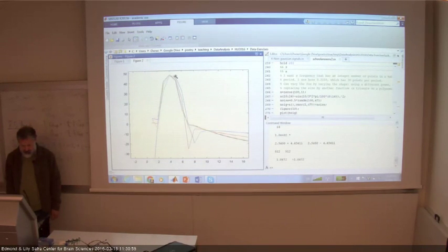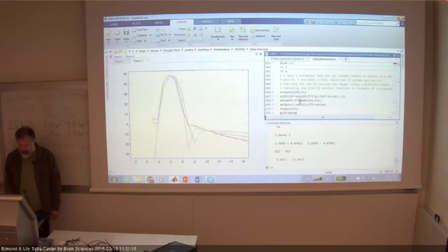And you can see how the interpolated peak frequency slowly shifts, if you wish, from 3.5 down to 3. Again, this is plotted in terms of indices, so it's above index 4. But the window allows you to get something that looks intuitively more like what you would call a power spectrum of 3.5 hertz sine wave or whatever.